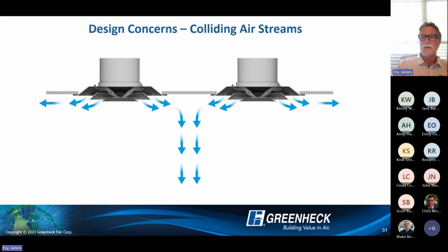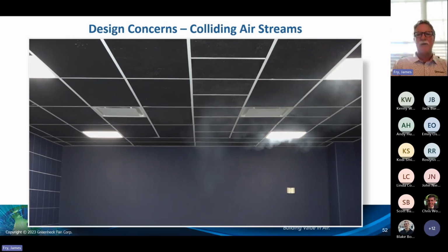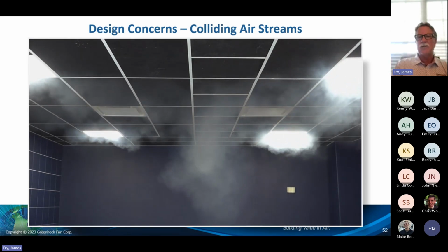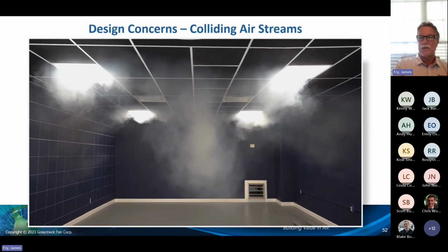Some concerns. Here's an example of some colliding airstreams. More is not better. Bigger is not better. You have to provide the right product in that air. So we don't want to put diffusers next to each other. It doesn't utilize the effects of the throw. Here's an example of that same diagram that we showed you. The air is going to come out. Instead of holding that ceiling and going to the wall like we want it to, it's just going to dump straight down and create a draft right in the middle of that room.